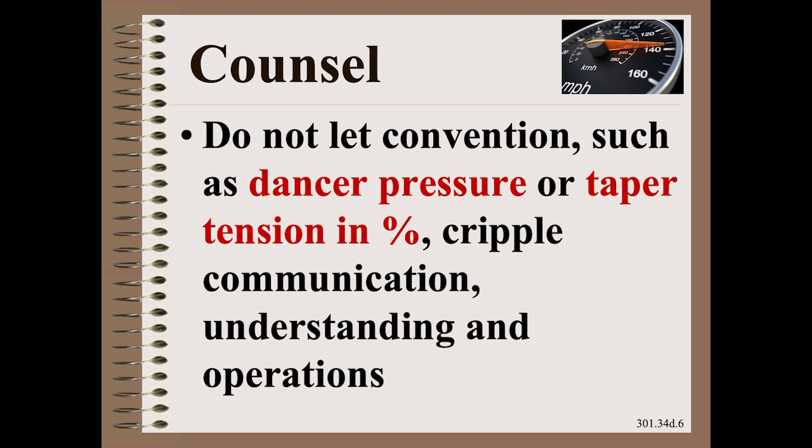Let's summarize. Do not let convention, such as dancer pressure or taper tension in percent, cripple communication and understanding and operations. Calibrate your old machine. This is an excellent project for an engineering student or a new hire. Do not let any new machines in your building unless they are calibrated and calibratable in proper web units.